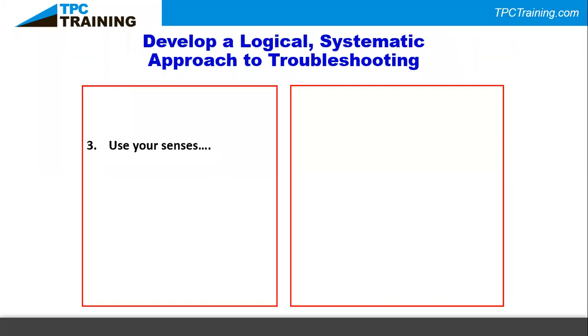Like in the case of electricity, using that multimeter to poke around and try to figure out for yourself what's happening. And in that case, you're going to have to start tearing apart the equipment, opening panels, doors to start doing some troubleshooting. And that's really the first step you need for any good troubleshooting process from here on out, whether it is mechanical or electrical troubleshooting, is getting your proper PPE for the job. So in the mechanical world, that's the proper gloves, proper guarding, proper lockout tagout procedures before you start digging into equipment and taking a look.